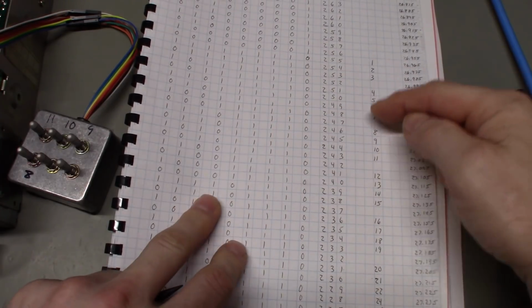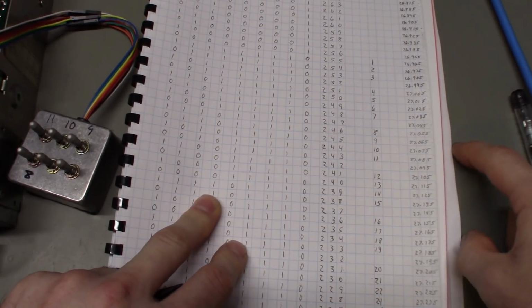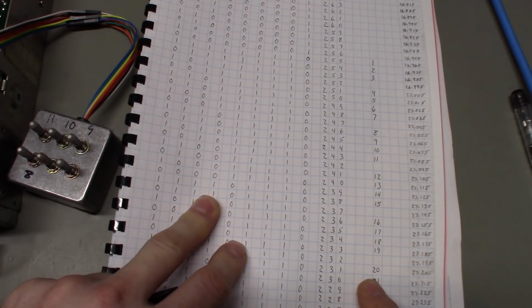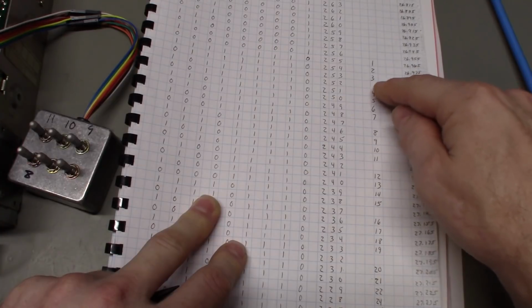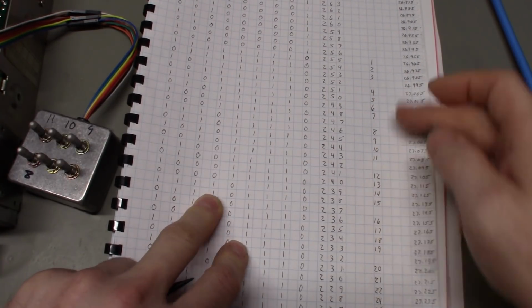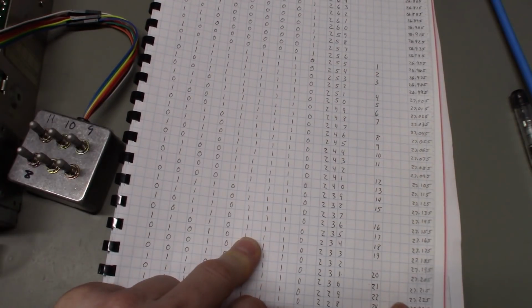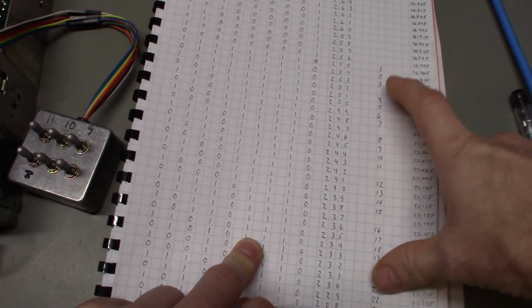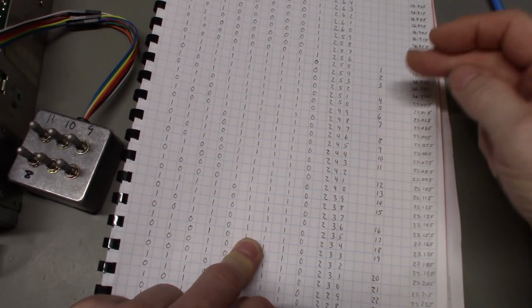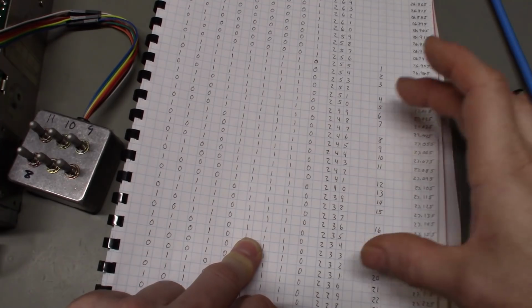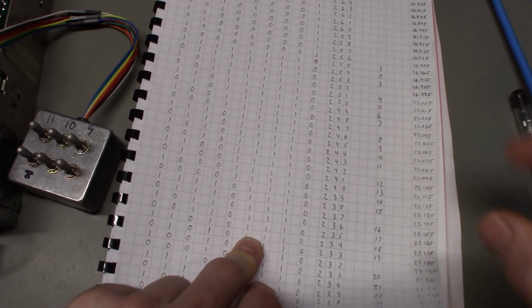So these skips are going to continue. If you get an additional 40 channels above the normal 40 channels, it's also going to have these skips in the same exact locations. So for the normal CB band, there are actually 45 frequencies there. Only 40 of them are used on CB, but there's 5 of them that are missing. And that block of 5, those skips are going to carry over to the next chunk.